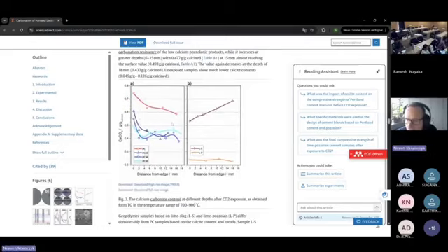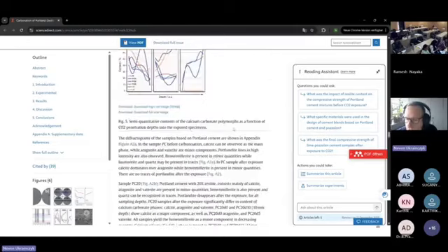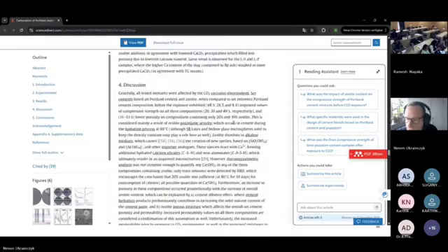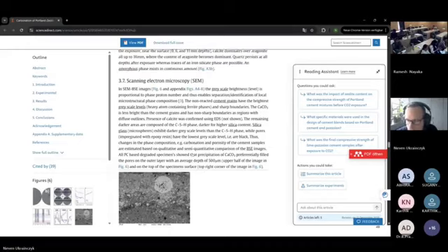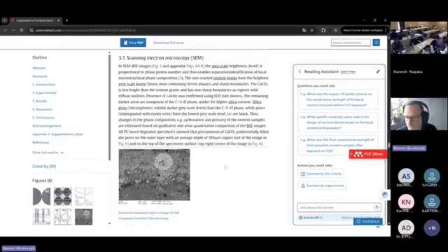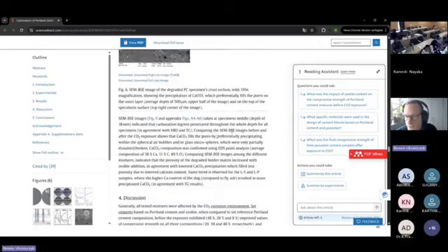Maybe I can show some TGA curves. This I will show you tomorrow. This is how all this calcium carbonate filled all the pores in the cement paste. This is the surface level of the sample, and the calcium carbonate basically filled all the pores, even the big pore, the air bubble pore, everything filled with calcium carbonate, because this is CO2 under pressure.